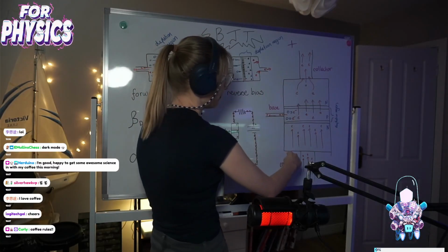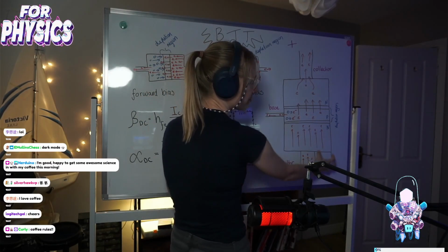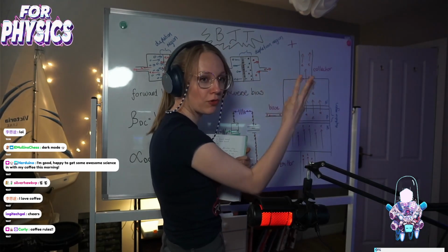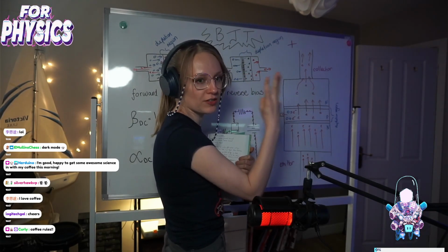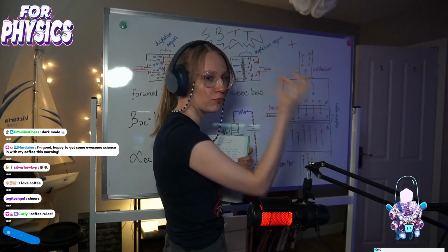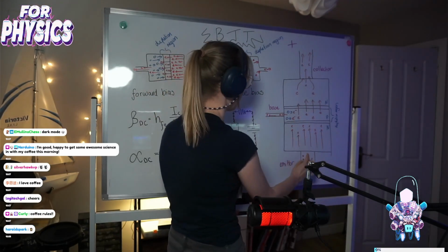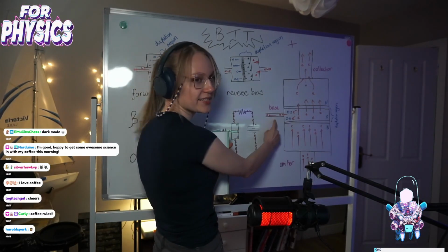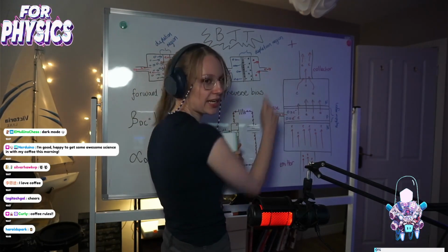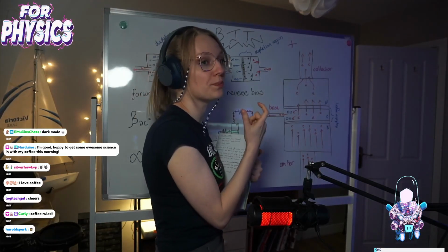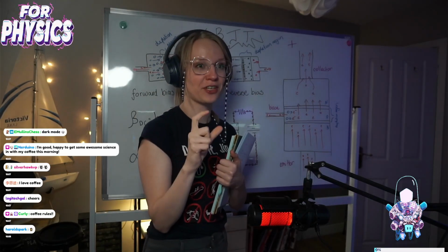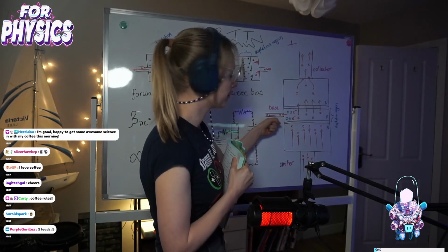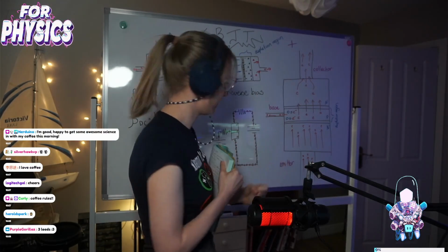This is zoomed in. This part here is called the emitter of the transistor. So remember, there's 3 rods coming out of a transistor. 3 rods. Holes are a different thing. There's the emitter at the bottom in this case, the base in the middle, and at the top is the collector. The middle will always be the base, by the way. So the only thing you always have to figure out is which is the collector and which is the emitter. But the one in the middle is always going to be the base.